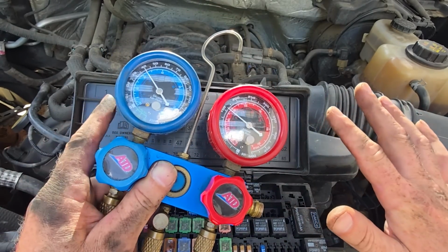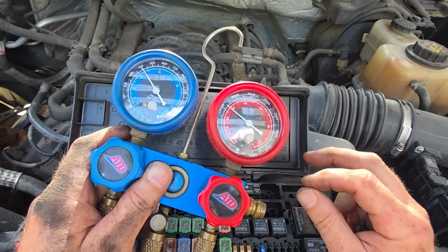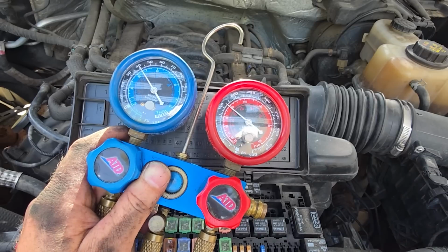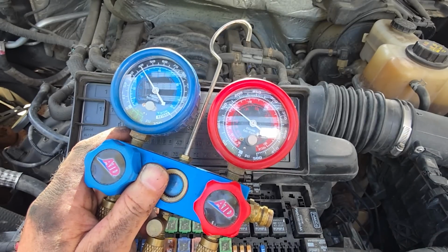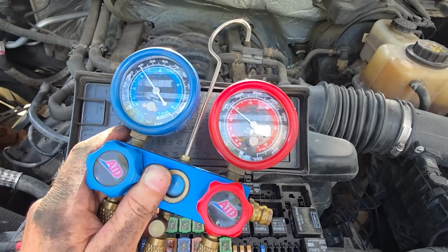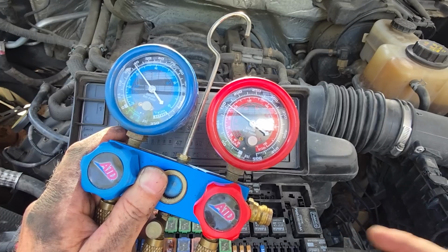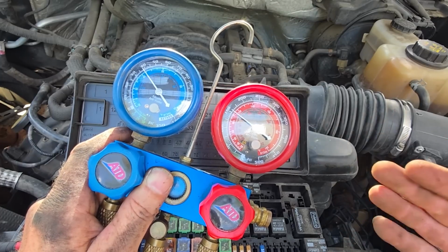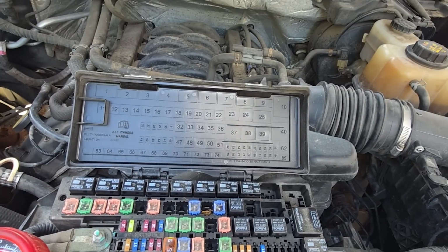It is absolutely a little bit low on charge. Not the main point here of what we did. What we had was a compressor clutch connection issue right at the connector itself. That is a win right there. And he can top this off with the refrigerant he bought at a later point. The main part of this was troubleshooting a clutch that was not engaging, and it was not from a pressure problem, it was from a connection problem. So Rick, all I need you to do is drive it. We'll re-secure that harness. Drive it, let me know how it is. It should be consistent now.